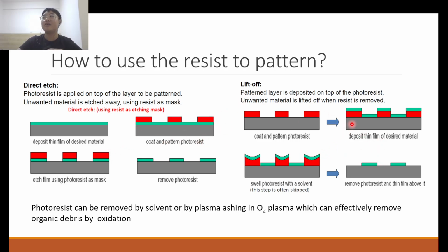But lift off generally tends to cause more contamination, because when we lift off the film that's deposited on the photoresist, it could drop back on the wafer and things like that. It could cause particulate contamination, right? So we just need to take note of that.